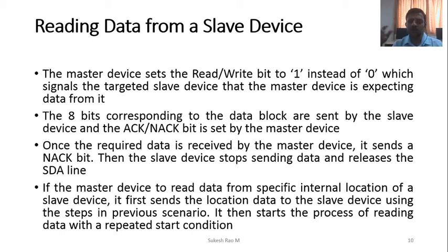Usually anybody who designs a system, nobody will go that way now, except in some exceptional cases. If there is a requirement for an ADC, then only they prefer it. Otherwise it's all system on chip now. We get an ASIC device for temperature sensing which has I2C or an SPI protocol. The advantage is you need to communicate with fewer IO lines, and you don't have to have an ADC and all that. It's all calibrated, so you can get the ready reading and put it on the display. That's why they prefer I2C. That's why I2C is important.